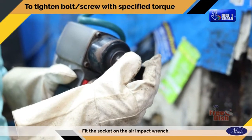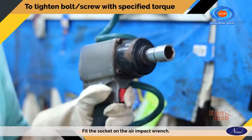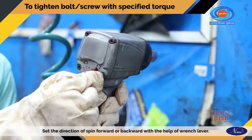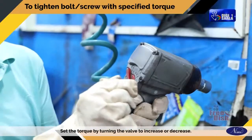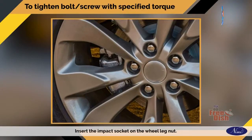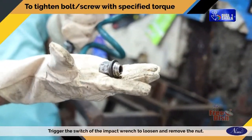Fit the socket on the air impact wrench. Set the direction of spin, forward or backward, with the help of the wrench lever. Set the torque by turning the valve to increase or decrease. Insert the impact socket on the wheel leg nut. Trigger the switch of the impact wrench to loosen and remove the nut.